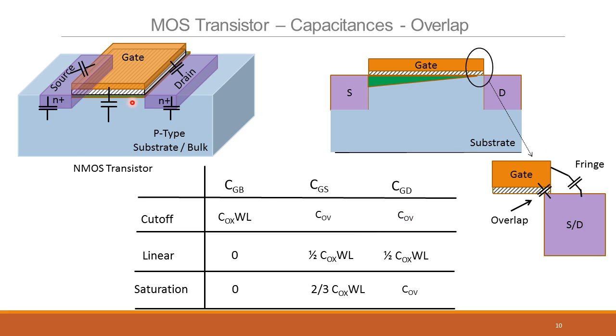Of course, it depends on the W, it doesn't depend on the L. If you notice, L is this geometry, and that's a design parameter. That capacitance doesn't depend on L, but it depends on this amount of overlap here. Hence, it depends on W for sure, because the more the width, the more the overlap capacitance. But the length has no impact, because this distance is not governed by the length at all. Okay.